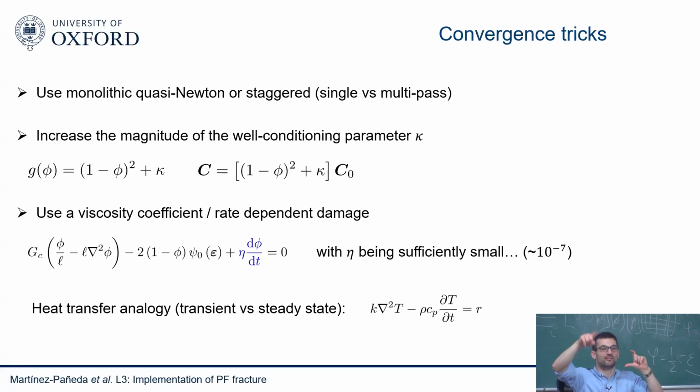It might be that the internal Newton-Raphson for plasticity is completely lost, because suddenly you had a situation where a crack was growing stable, and suddenly the crack grew in an unstable fashion, and a point which had some load carrying capacity, the next increment has no load carrying capacity anymore. So the plasticity algorithm is lost because the stress field is very different from the previous iteration. So some things like this can happen. So there could be problems where you get convergence issues. In linear elasticity, I don't remember ever encountering any convergence problem if you use the right solution schemes.